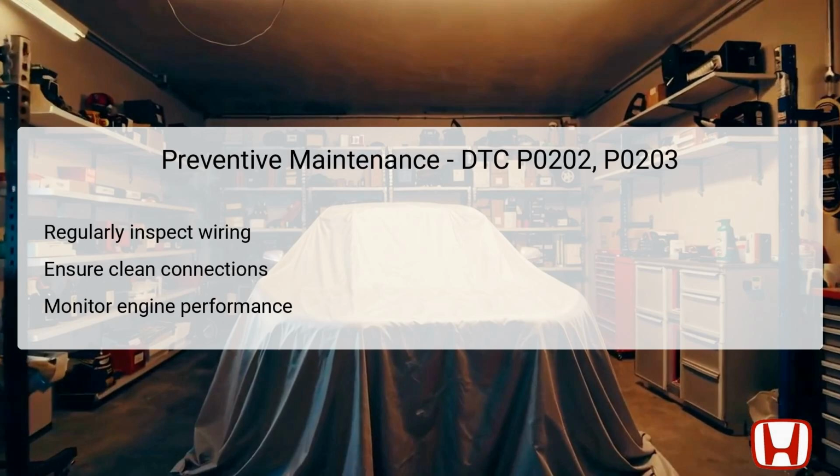Preventive maintenance is essential in avoiding future occurrences of DTCs P0202 and P0203, as well as ensuring the overall health of the vehicle's injector system. Regularly inspecting the wiring associated with fuel injectors can prevent breakdowns caused by frayed or damaged wires.